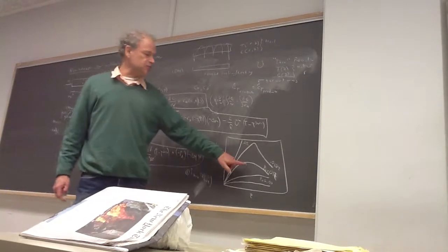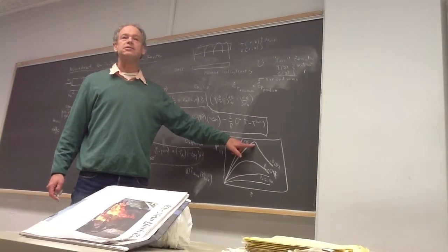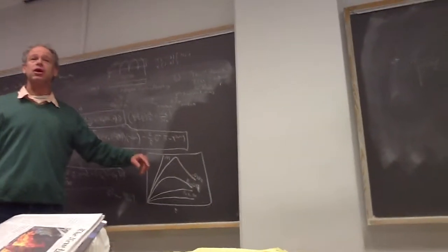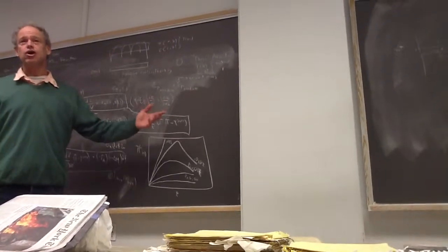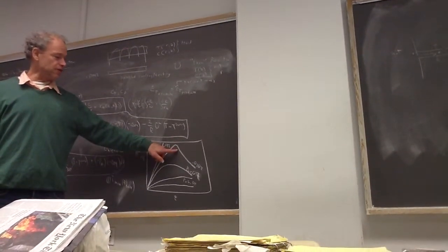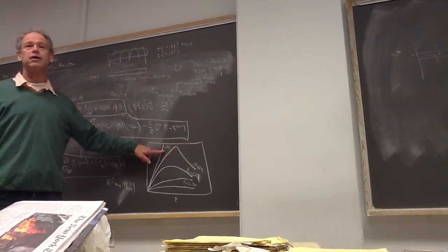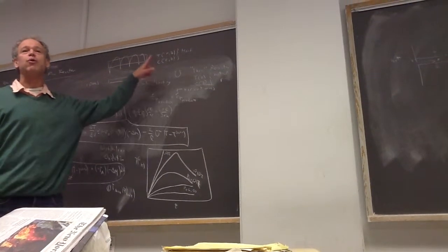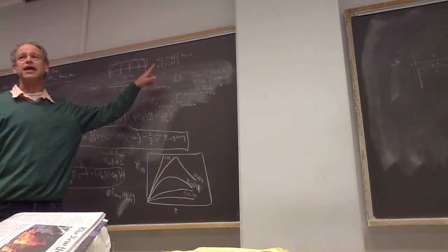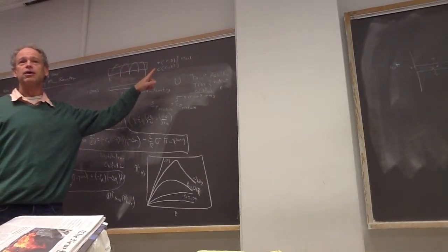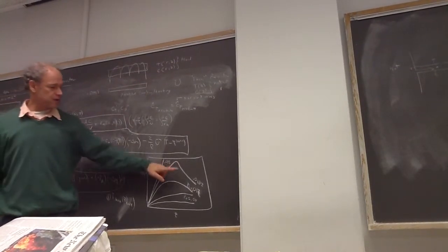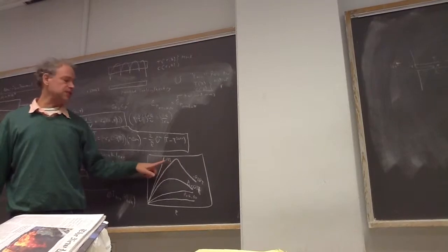And that's the real dangerous spot. If T max is too high, I can fry the catalyst. Well, frying the catalyst is a bad thing. Costs money. However, if I go from 0.0182 to 0.019, look what happens. This curve just keeps going way up. And there, now you could get into a dangerous situation where you could have an explosion. And there isn't very much of a difference in the partial pressure between these situations.